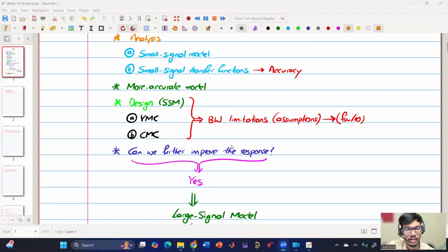Yes. So one good thing that you have pointed out is whenever we are considering large perturbations, the small signal model will not be applicable. So in that case, we have to consider the large signal model. In addition, when the transient requirements for my application are higher, and the small signal model is not able to reach that fast transient response because of the bandwidth limitation, then we have to go for the large signal model.